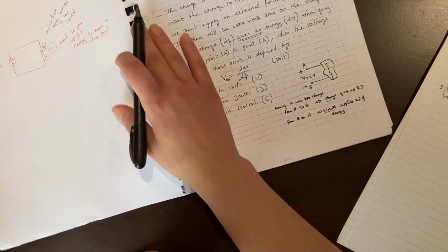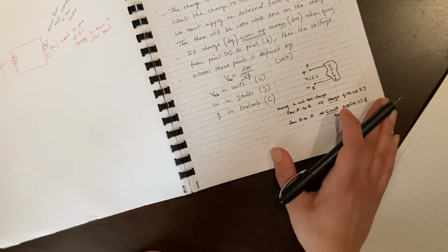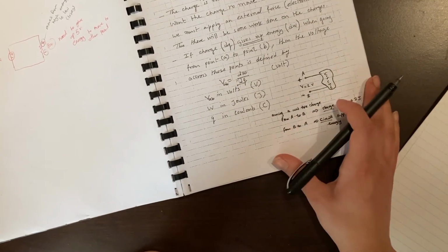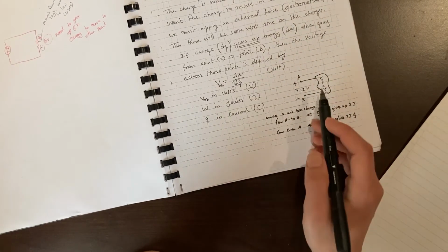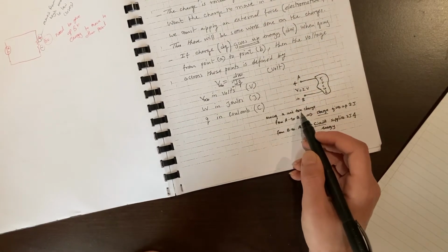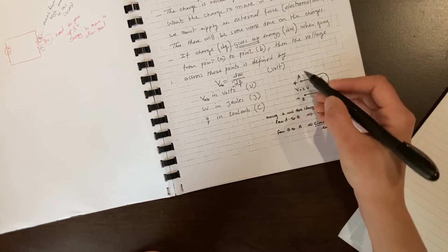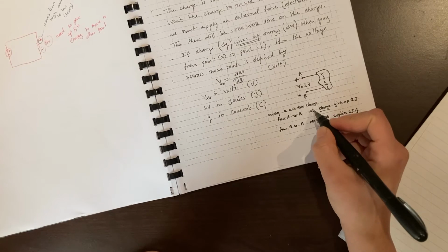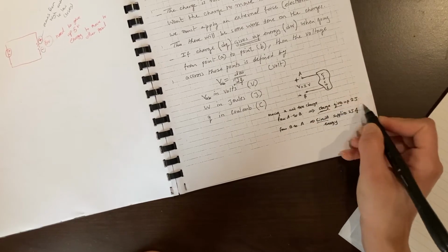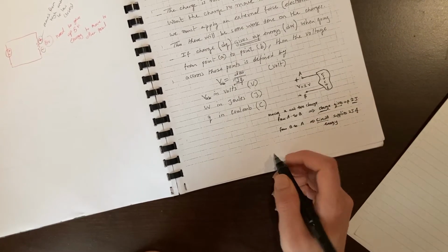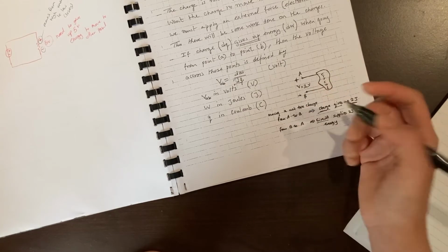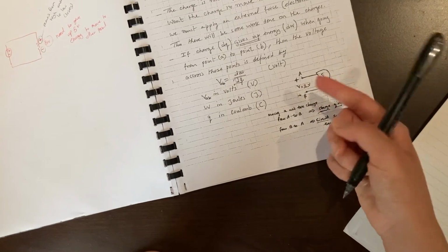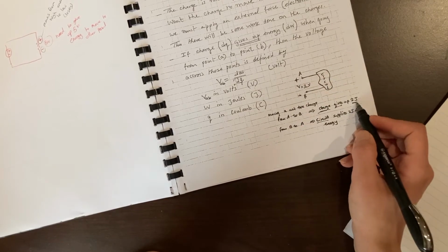Again, we noted how the current has a direction, right? So does the voltage, it has a polarity. So what does it mean? It basically means that moving a unit of charge from A to B, so we're going from higher potential to lower potential, the charge will give up 2 joules. Because we have 2 volts and 1 coulomb of charge, we just multiply them. So 1 times 2 is 2, and you get back the unit of energy.